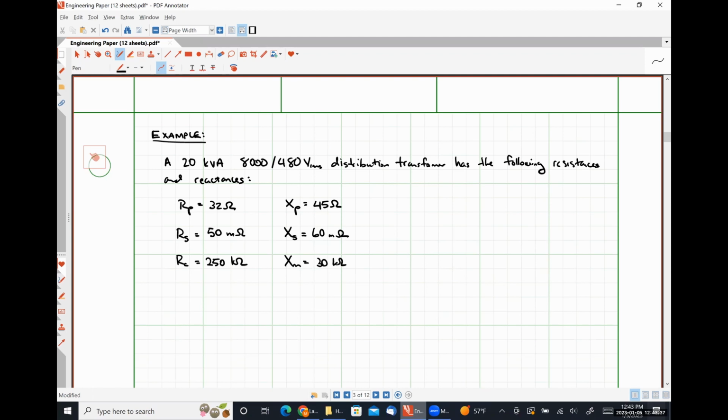impedances, probably on the order of kiloohms, because if they're small, that means we have a very inefficient transformer, right? Similarly, our series pieces should usually have relatively low resistances on the order of ohms to hundreds of ohms, because if they are any larger, we also are going to have an inefficient transformer, all right? So what I want is for us to do our cantilever equivalent circuits, referred to the primary side and the secondary side. Pretty straightforward things.